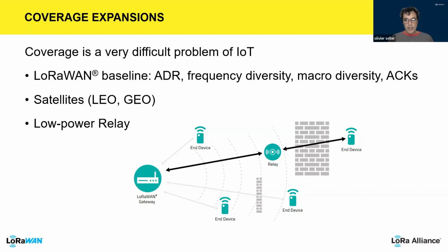And with LoRaWAN and the dedicated data rate and physical layer, we can have direct connectivity to satellites because of the long range, and still at a low transmitted power and reasonable time on air. So in that case, it's very long range and still low power. It uses either ISM bands, typically the LEO case, or licensed bands, and typically the geostationary satellites use licensed bands. We need satellites because in many areas, terrestrial networks are just not viable economically.